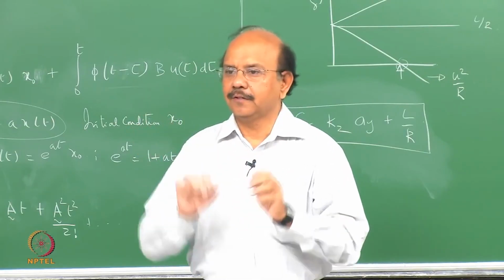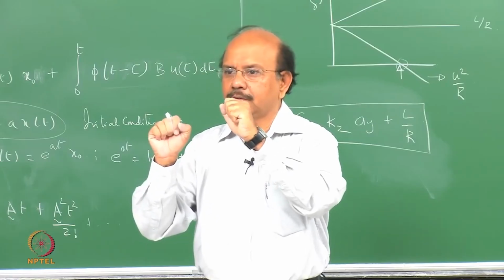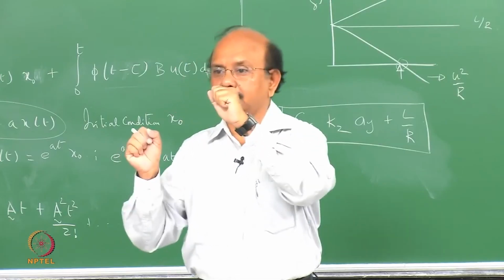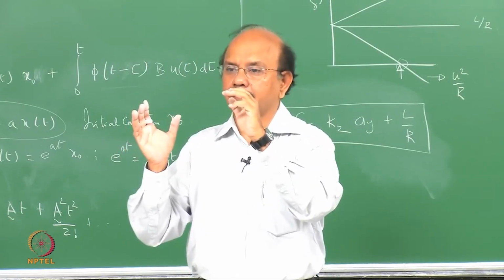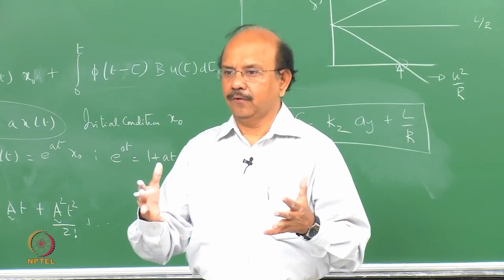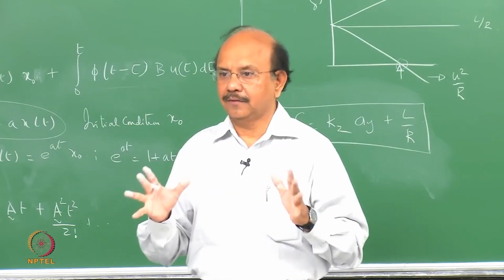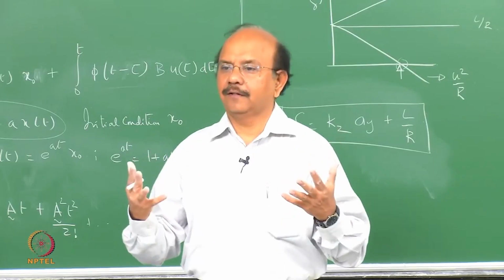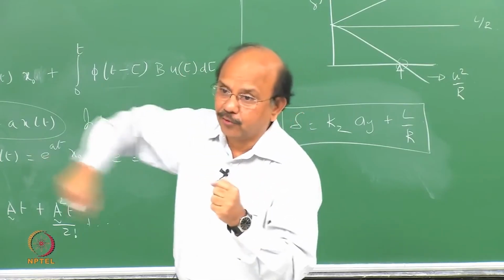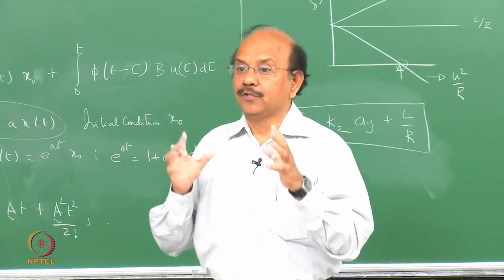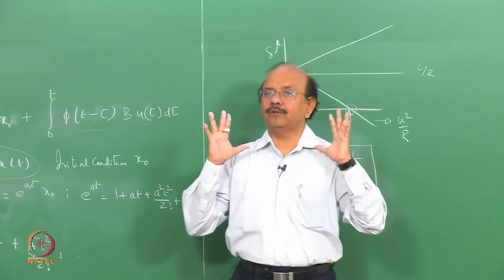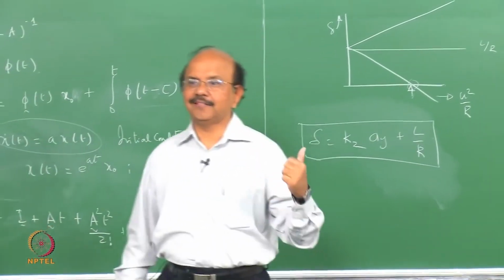Let's say that you increase the velocity. The steering which you have given, you now have to make it smaller. Now further increase the velocity, and again you will make the steering input smaller. At one point of time, you are not going to give any input to the steering, and the vehicle will go around at one velocity. You increase the velocity further, you will have to give the steering this side in order to go in the clockwise direction. So the point at which you give zero input to the steering is that critical velocity.